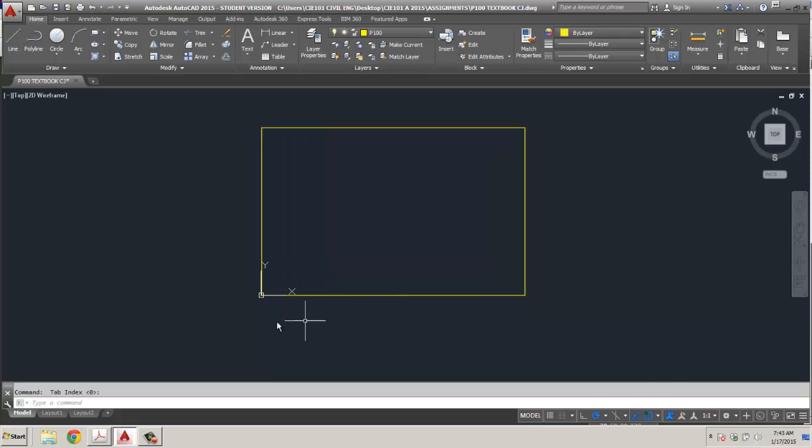So if I'm back on my line tool, there's my end symbol. Now if I wanted to find the midpoint of this line, see how it gives me the triangle? It'll find the midpoint. It can find the midpoint on any of these lines. If I was drawing a line straight down, you don't have to do this, but just so you can see how it works, when I come down to this point, it pulls up the triangle.